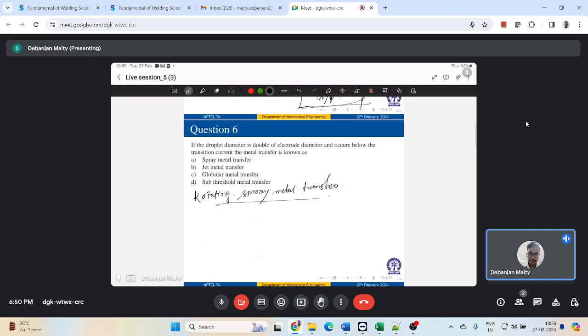Here the electrode tapering effect that was happening during streaming spray is more pronounced, right? There will be more overheating, and heat formation will be more and more over here, and strong electromagnetic force caused by this excessively high current will result in some rotation of your column away from the straight line flow, right?